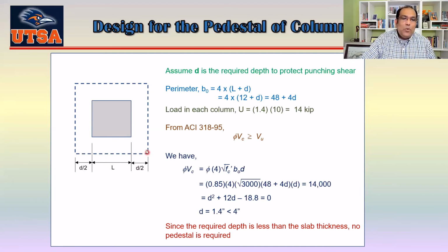So we have to put maybe a 2 feet size pedestal, with 6-inch depth or more, below the slab.